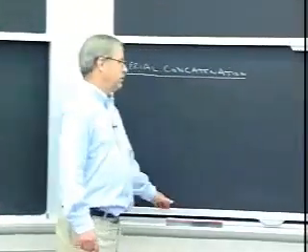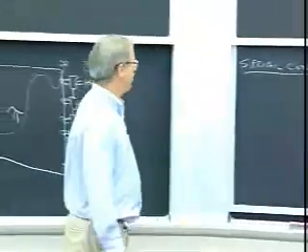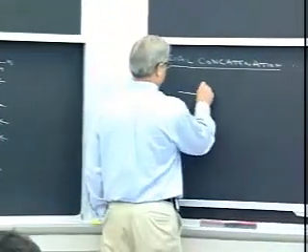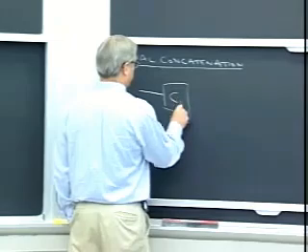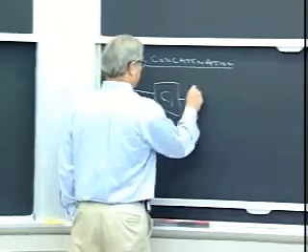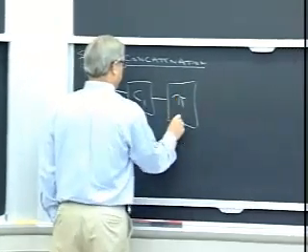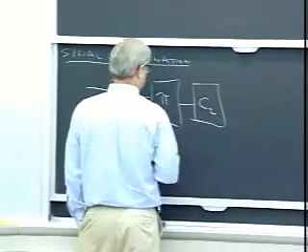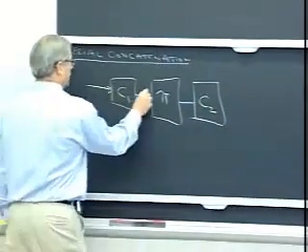All right, well, we can come back to this at any point. Serial concatenation. Here the idea is you basically go through one code, then you interleave, and then you go through another code. This is the kind of setup